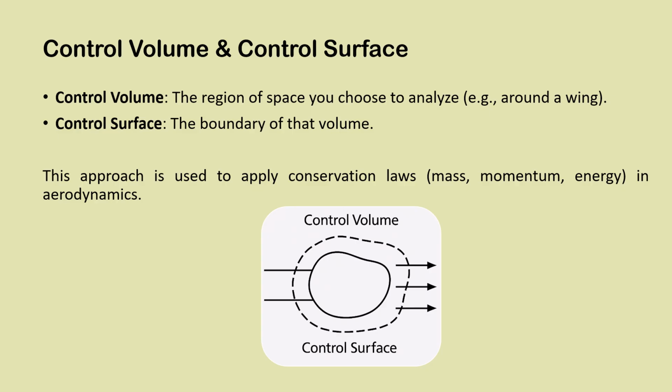Control volume and control surface. A control volume is the space or region you choose to study. The control surface is the boundary of that volume. We apply all the basic laws like mass, momentum, and energy over this region to understand fluid behavior.